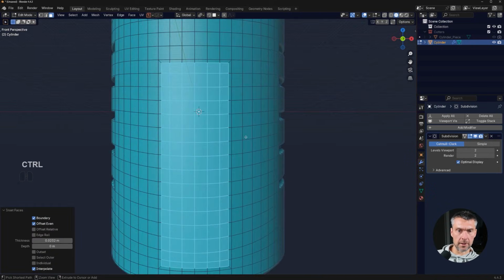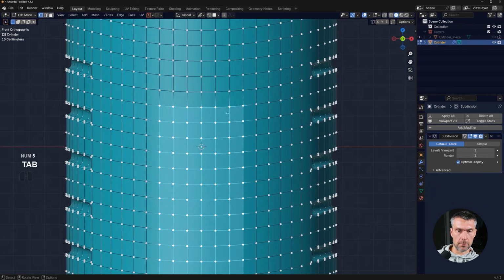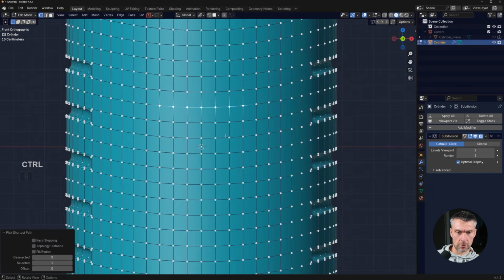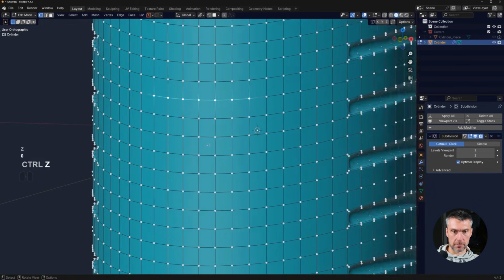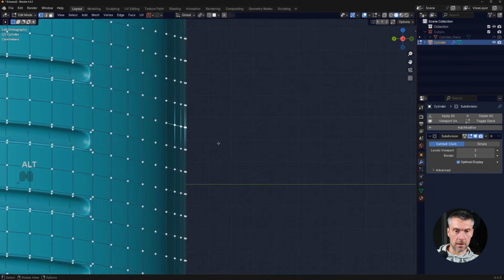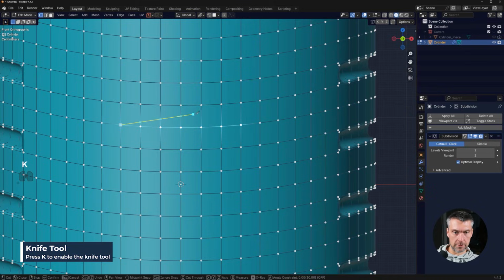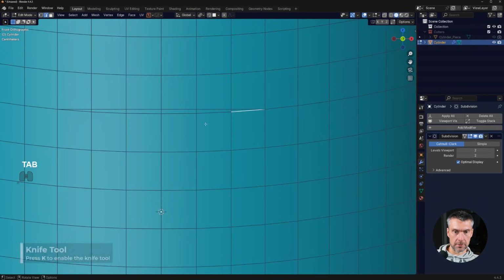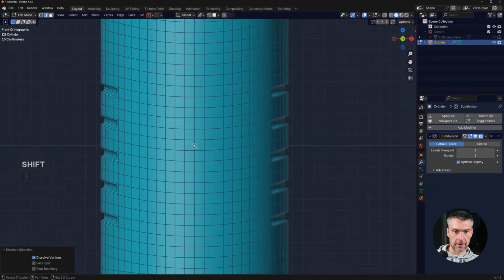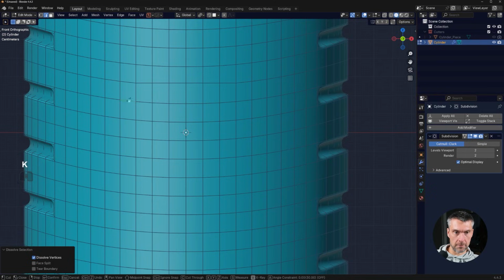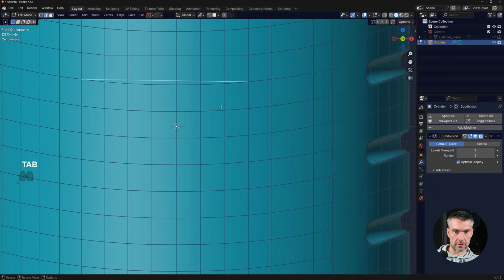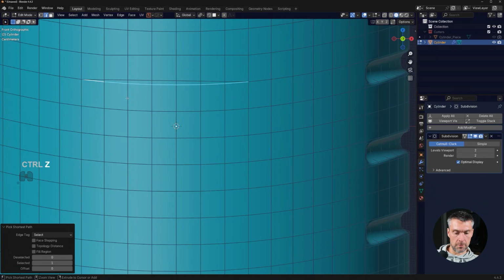In fact, before I do that, let's make sure that this top part here is actually straight. So we need to straighten this up, okay? Now the way to do this, right? You can't really do SZ0 because you're gonna mess up the shading. What you could do is run a knife cut in between them here like this, right? And then simply delete these, okay? So Control X, right? And then the bottom one doesn't matter, only the top one. Actually, this one maybe still should be straight, and this one should be removed.